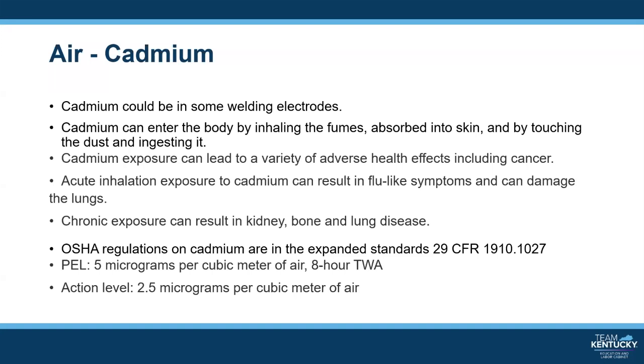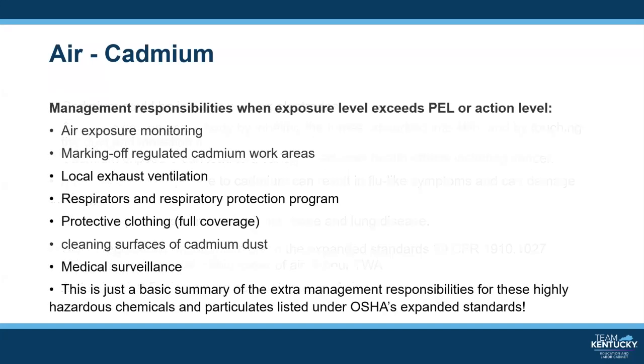The action level for cadmium is 2.5 micrograms per cubic meter of air. When cadmium is used in the workplace and could create these hazards, management would have extra responsibilities when the exposure level exceeds the PEL or the action level.